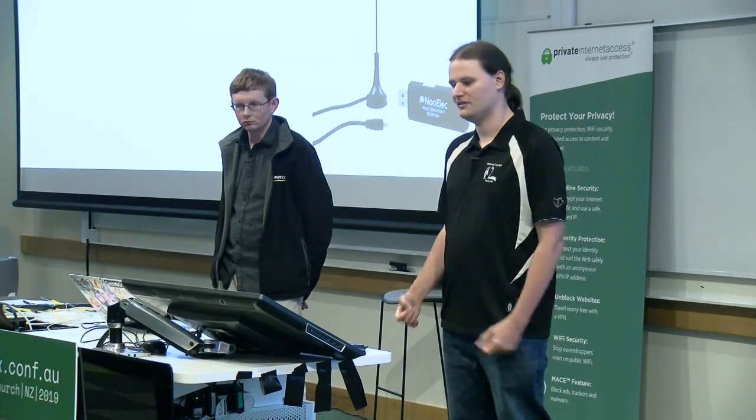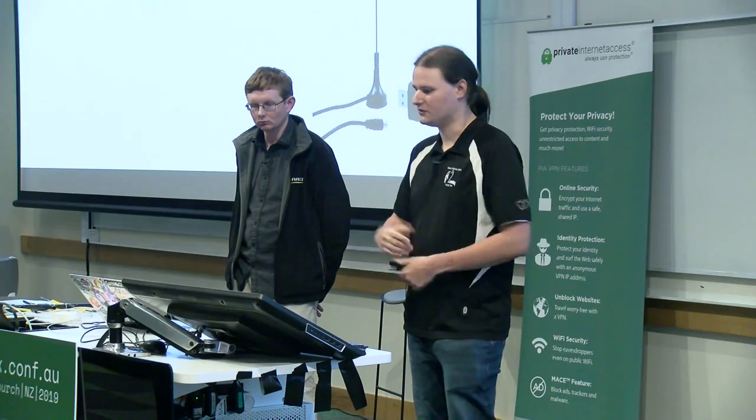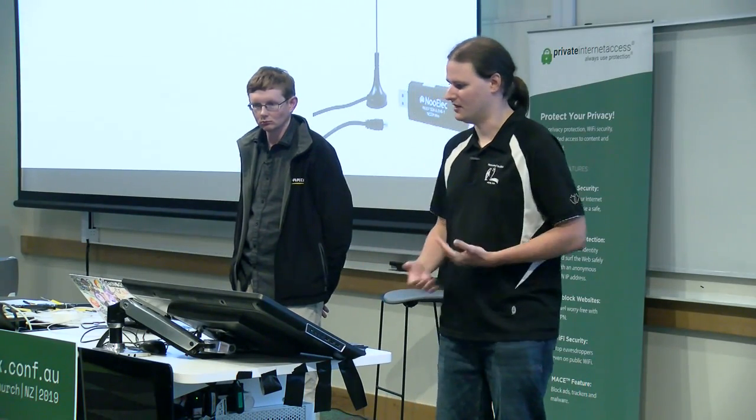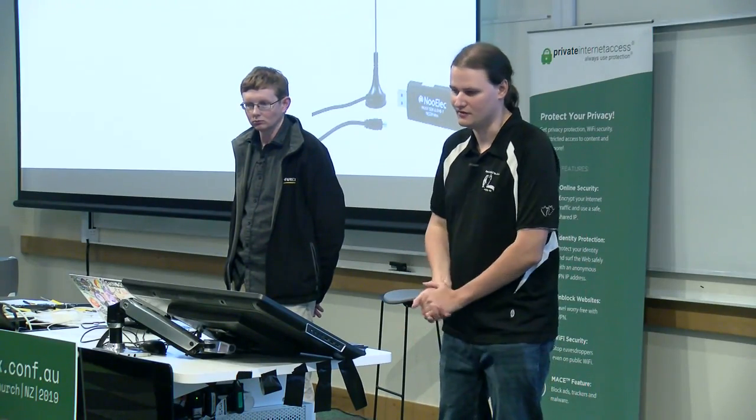The other thing you'll need is a stock antenna. Usually the default one from the RTL SDRs that you can get, the little stubby magnetic one, is usually good enough. It's not great, but it's good enough to get going to start with. If you want something better, say if you want to receive sondes from really far away or weak sondes, you can build yourself a quarter wave ground plane antenna. There's lots of instructions online on how to build one, but basically it's a few pieces of wire at 18 centimeters long, arranged in the picture there.